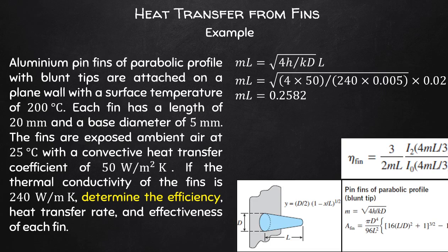On that note, do not ever give decimals to Reynolds number. Reynolds number is a qualitative number. We will also come to grips with other qualitative numbers in heat transfer. The decimals aren't important. What is important is how do you interpret such numbers.